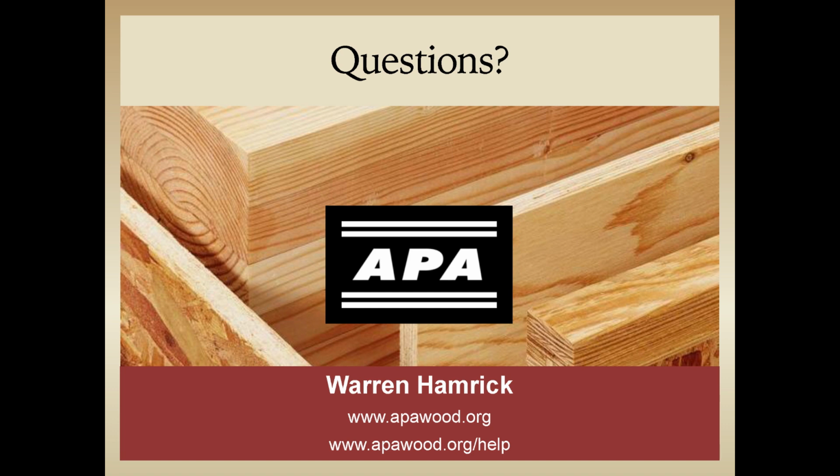Wonderful. That's my understanding too. As long as you're designing per the IRC, and if you're working with an engineer, talk to your engineer about it, my understanding is that no matter where you are in the country, it shouldn't be a big deal. We will make sure to clarify that on our posted Q&A later. If they're talking about an IRC design, then yes, you should be able to go to that 24-inch spacing and still meet those requirements.